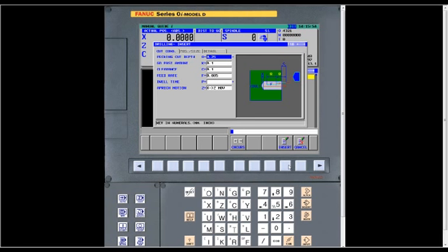It shows a picture of what it's doing, and it has the Q highlighted. The first thing it asks for is a pecking cut depth, and we're on cutting conditions for drilling. You can see next to this it has an asterisk. Anytime a cycle has a field with an asterisk next to it, you don't have to answer that information. It's optional. But in the example I have here, I did answer that part of it.